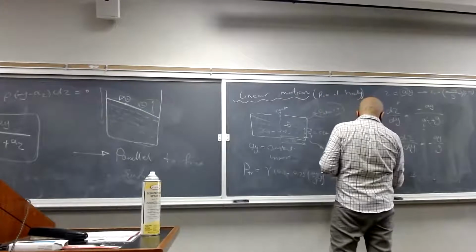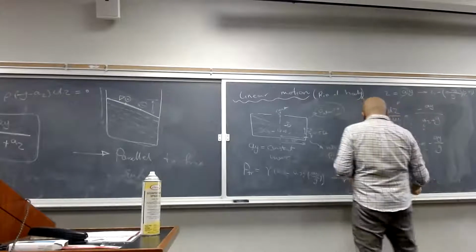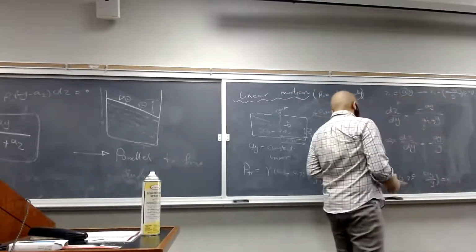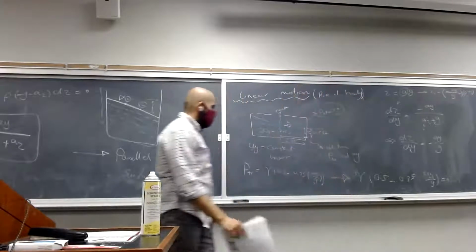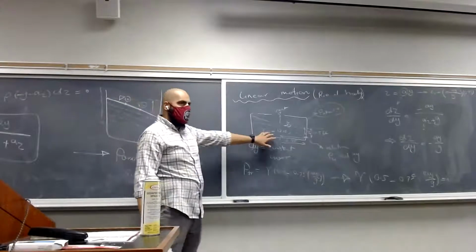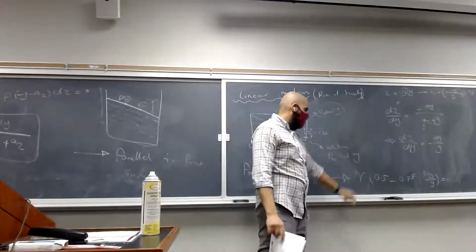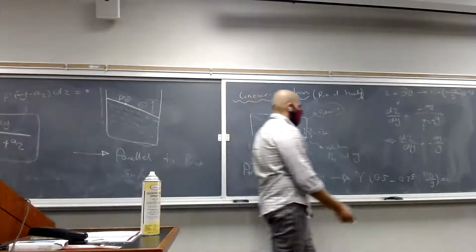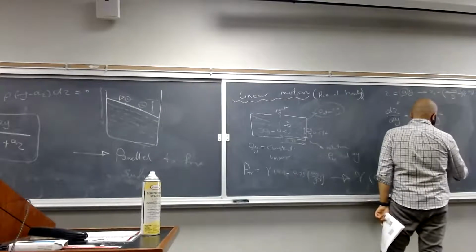So to find that maximum acceleration, we only have to put pressure equal to 0. So we're going to get gamma minus 0.75 AY divided by g equals 0. You have the gamma, that's gamma of fuel, which is going to be, we have the specific gravity of fuel, so we just have to multiply this value by the gamma of water to find the gamma of fuel, right? We have the gravitational acceleration. We will be able to find this maximum value, AY max.